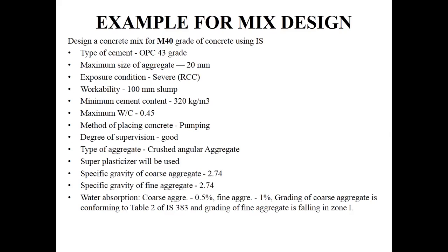We will be getting these values, like the specific gravity of coarse aggregate and fine aggregate, and the grading values, using experiments in the laboratory. Only by that will we get these values. They are not simply given in the question itself. When you are making a mix design, you will have some collection of materials, cement, sand. So you have to study the properties of the cement before going for the mix design. You will conduct the specific gravity test for cement, and for coarse aggregate and fine aggregate, and then only will you get those values. Since this is a problem, they have given the values straight away.